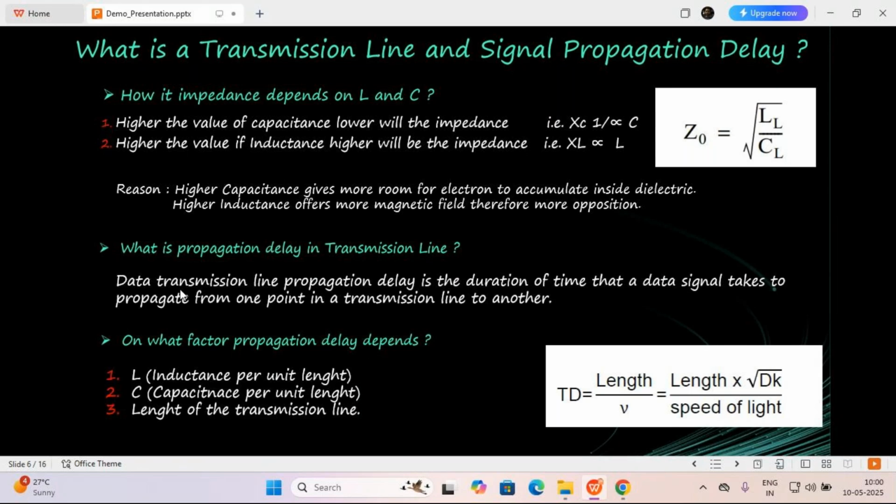To form a capacitor, the minimum requirement is two metal plates, which are the two copper plates here, and a dielectric insulation, which is the dielectric material of the PCB. Different types of dielectric material are chosen based on our design requirements, in order to maintain a proper impedance as well as to keep losses low. We will learn in the signal integrity course how to choose the prepreg and how to design the stack up.